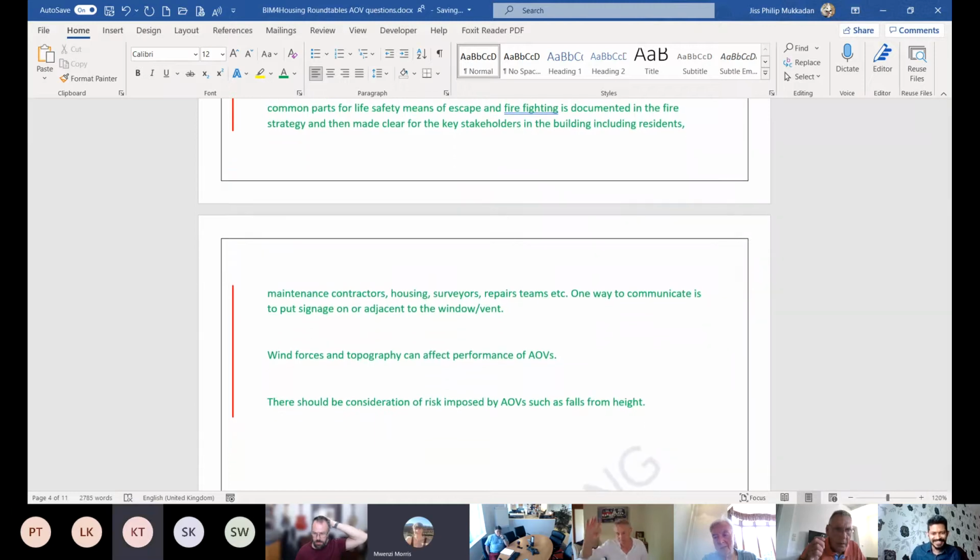I think the short answer to your question is the last part of your point is no, because if you use Approved Document B and just follow the guidance verbatim, there would be no requirement to consider surrounding buildings other than for B4, as in fire spread between buildings.